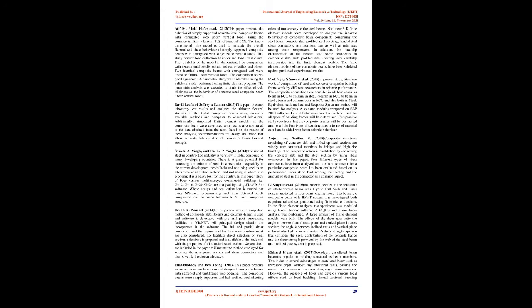In addition, the load slip characteristic of the headed stud shear connectors in composite slabs with profiled steel sheeting were carefully incorporated into the finite element models. The finite element models of the composite beams have been validated against published experimental results.